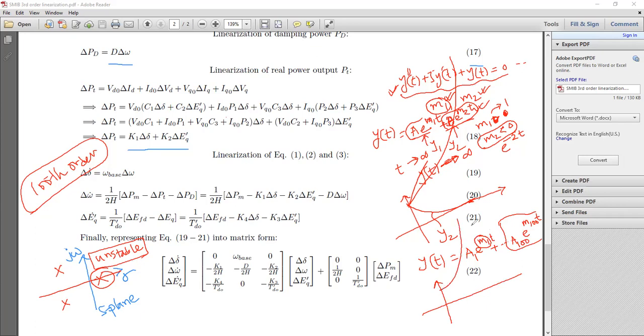The single unbounded response for y1 is enough. Let's say all the other 99 die to 0, but because we finally have to add up this one and the remaining 99, the total response y(t) would give you an unbounded response. This is why even a single pole on the right hand side is not good for a dynamic system.